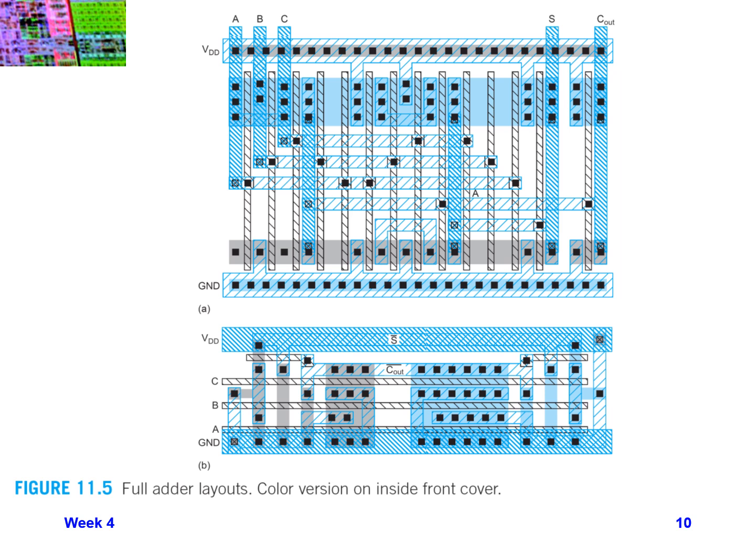Version A is our adder design, shown the way that we're typically doing layout in our labs, where our poly is vertical and we have the PMOS structures on the top, the NMOS structures on the bottom, and the design flows from the left side of the circuit on the left side of the layout through to the right side of the layout. So this design is more typical of how we would probably do it in the lab.